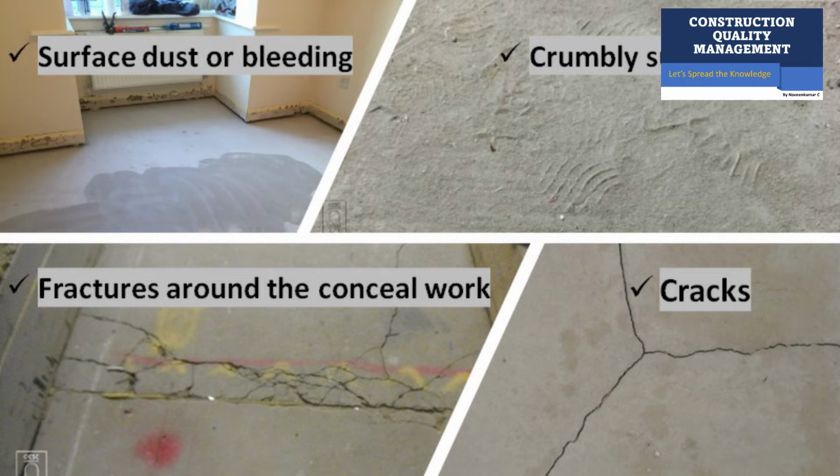And it doesn't fit any one particular type of screed. It is observed in all kinds of screeds, and the reason may be anything. The reason may be workmanship error, design error, or improper curing, or improper maturity period given to it.